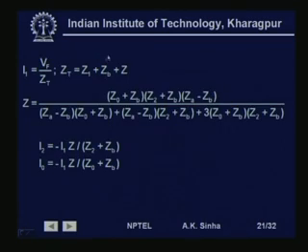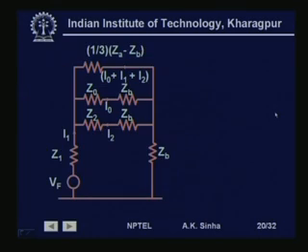So, that is Z, and we can write this Z is equal to (Z0 plus ZB) into (Z2 plus ZB) into (ZA minus ZB) divided by (ZA minus ZB) into (Z0 plus ZB) plus (ZA minus ZB) into (Z2 plus ZB) plus 3 times (Z0 plus ZB) into (Z2 plus ZB). That is, what we have done is reduce these 3 arms into a single impedance Z. Then we have Z1 plus this Z plus ZB, that is equal to ZT.